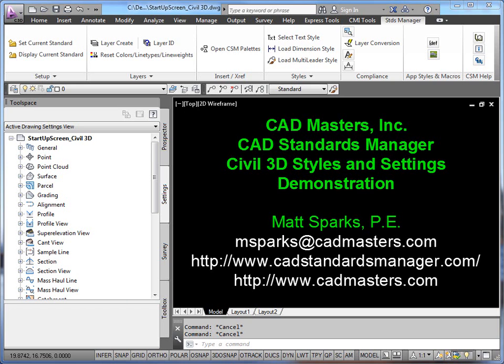Currently, Autodesk's solution is to use templates to push across any styles between drawings. While valid, this can become limiting as templates change and update. CADMaster stores these styles in an external database for retrieval from a central location. The advantage is the ability for the CAD Manager to edit styles outside of Civil 3D for standard content such as layers, blocks, and textiles.